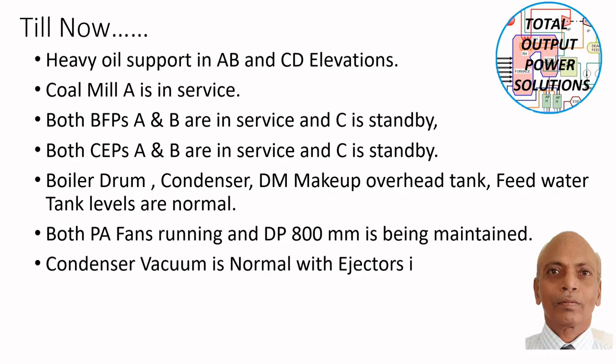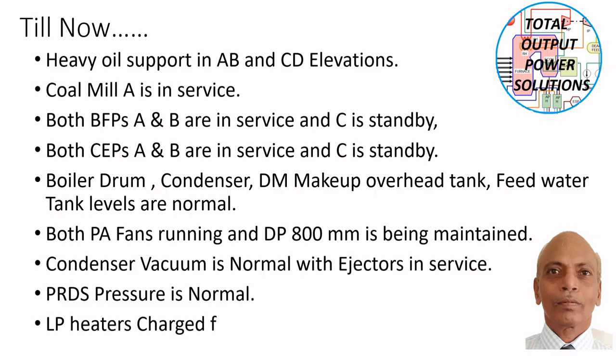Both PF fans are running, and a discharge pressure of 800 mm is being maintained. Condenser vacuum is normal with ejectors in service. PRDS pressure is normal. LP heaters are charged from the feed side.